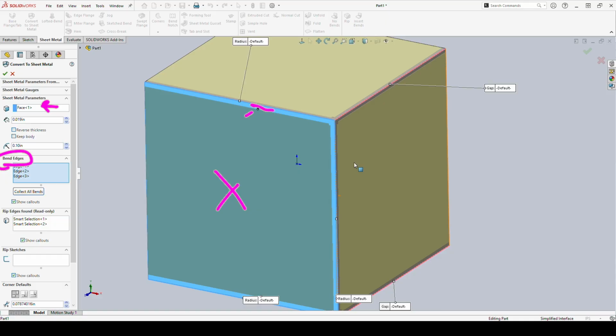This face and this face are connected, and they are connected by a bend of my material that went through here. And I'm also saying that on this, by selecting this edge, this face and this face are connected by a bend. And that means that the sheet metal flips up this way and the sheet metal flips down this way. So up like so, over like so.